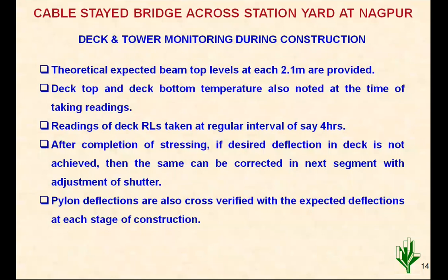Apart from that, there is a deck deflection due to temperature also. So you will notice that without any activity, the deck in the morning has some different level, and in the afternoon it has some different level. So there is a deflection due to temperature variation during daytime, and that deflection also has to be accounted for.